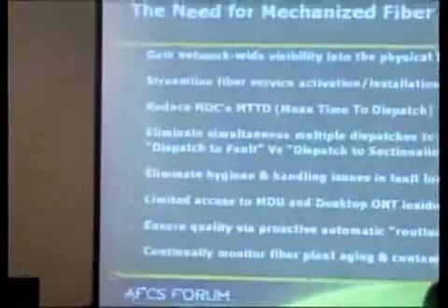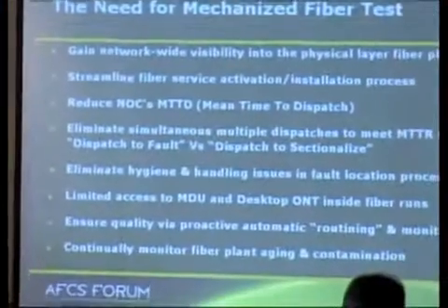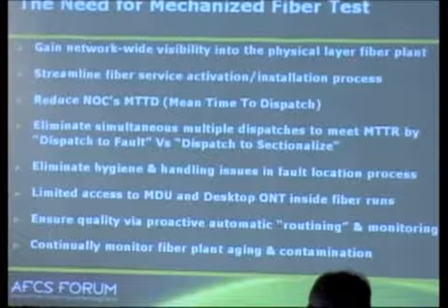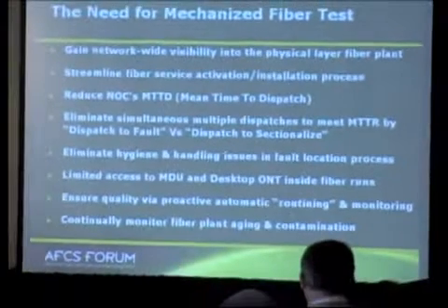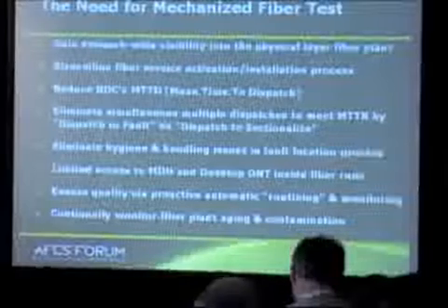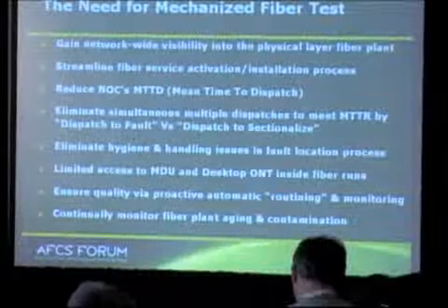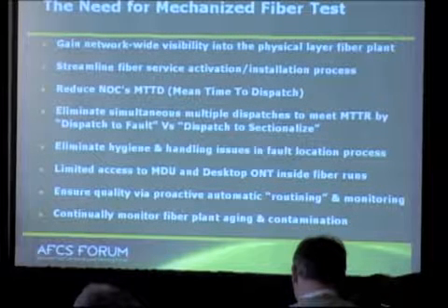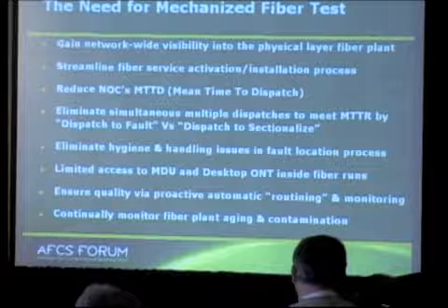Limited access to inside fibers. People, especially in MDUs, usually in larger municipalities, are also going to desktop ONTs. This is Verizon, as a matter of fact, going to desktop ONTs for their MDU deployment. In Europe, especially in Denmark, for example, desktop ONTs have great value.